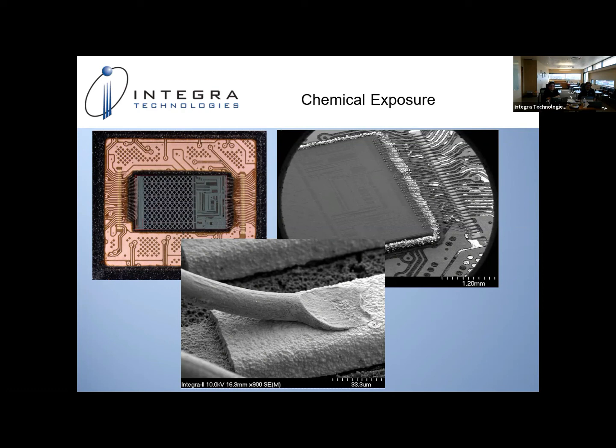Absolutely. No, that's a very good point. This is one of the results of our chemical exposure. And look at that, such a beautiful stitch bond, not a single piece of molding compound left on the wire, underneath the wire, on the pad. Next.